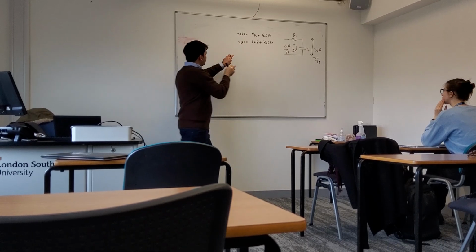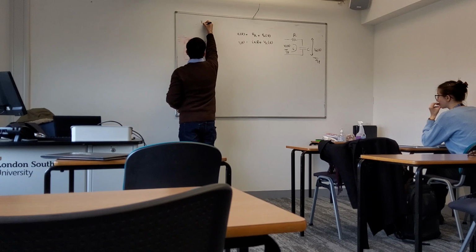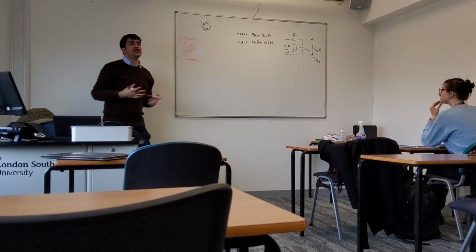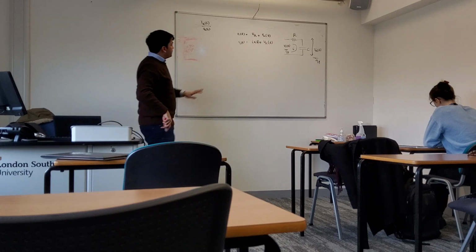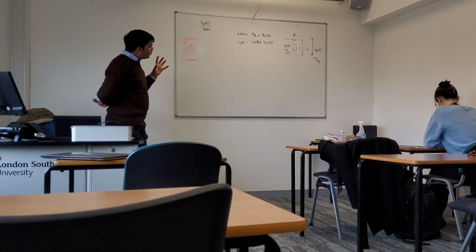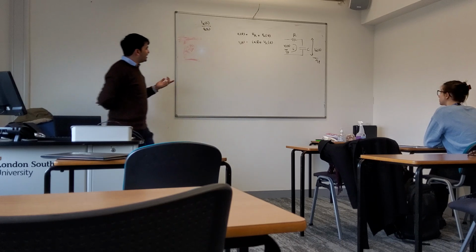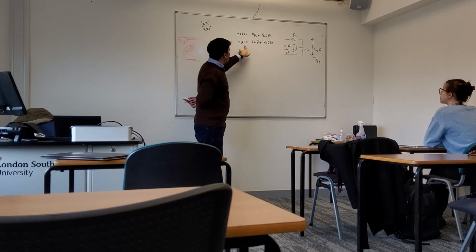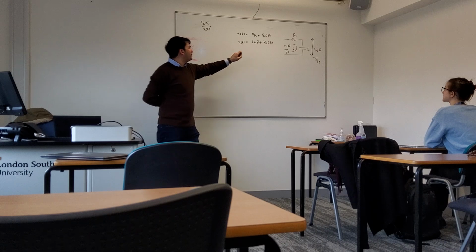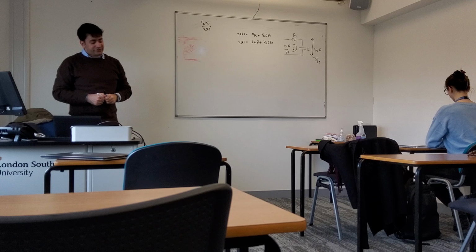Our main objective is to find the transfer function. And what is the transfer function? The transfer function is V2 of s by V1 of s. It means the relationship between input and output. We will see the transfer function later as well. Now, at the moment, we don't have a differential equation, and because we want something between voltages, we want this circuit to be all voltages. At the moment, this current is making a problem for us because it will not let us solve our system.